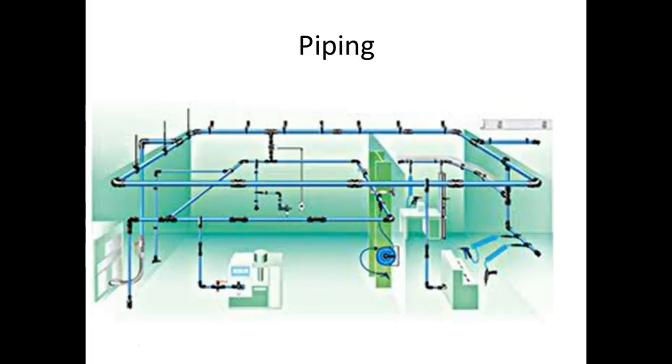Everything has a little pressure loss. And of course, what determines how much pressure loss you get in a pipe would be what's on that inside surface and also the bigness of the pipe, right? And so the bigger the pipe, the less pressure we lose when you start getting flow. So you don't get pressure loss if you don't have flow.